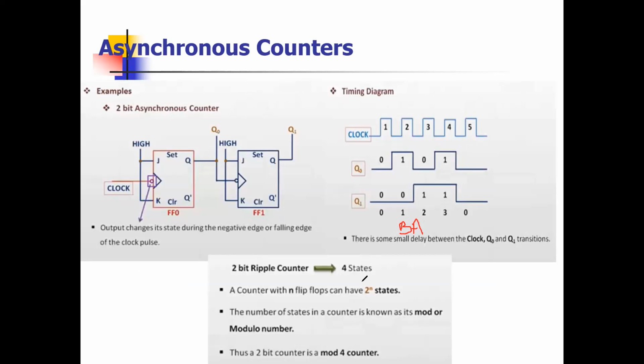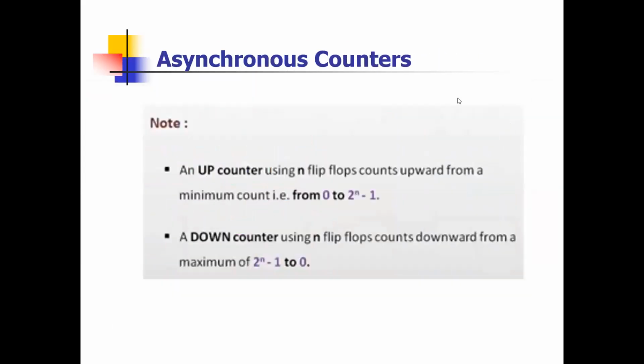Because here, look, if you write AB, with A as 1 and 0, you will not get the sequence. So what I do, you need to write B value first and then A value. So if I want to use it in the circuit, I have to switch. Clear? So now we have done the decade counter.